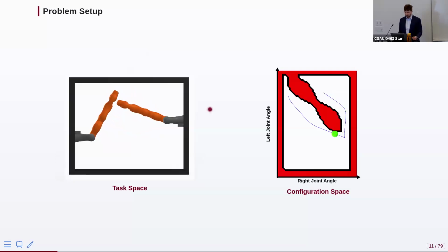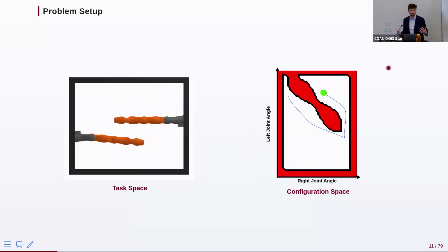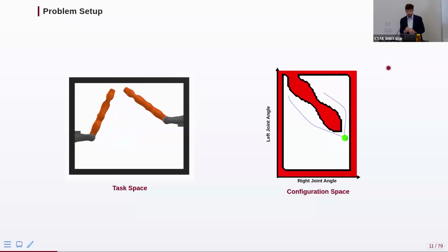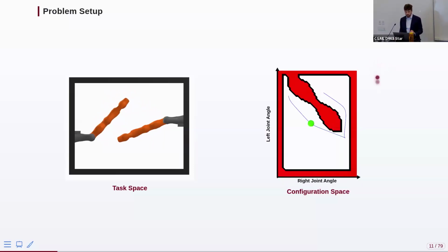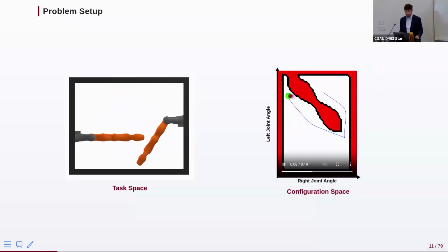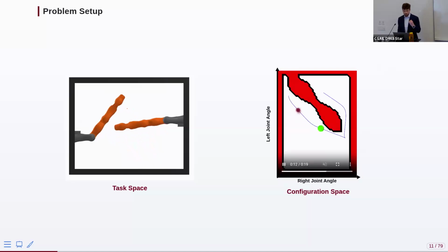Mathematically, roboticists think about doing motion planning by mapping each of these joints to a different coordinate axis. And this is what's known as configuration space. So here I only have 2 degrees of freedom, and so I can actually visualize it. But in general, my robots have a lot of degrees of freedom, and therefore this is going to be some arbitrary n-dimensional space. In motion planning for roboticists, the reason we like this space is that the robot becomes a dot. In motion planning, it corresponds to just finding some curve in this space that's not going to intersect the red region.